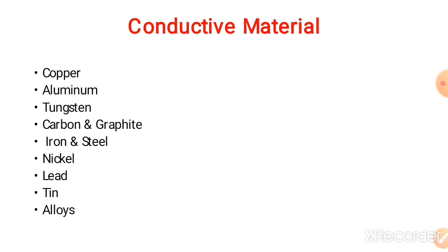Steel alloyed with chromium and aluminum is used for making starter rheostats, where lightness combined with robustness and good heat dissipation are important considerations. Cast iron is used in manufacturing of resistance grids used in starting of large DC motors.